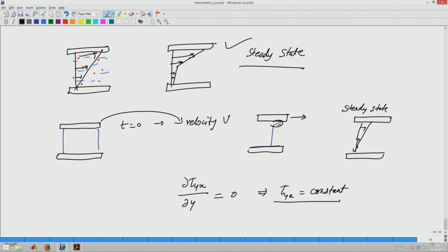There is a class of materials which show some density gradients, like what we saw in the case of particle gradients. Whenever such gradients are possible, it shows the shear banding phenomenon, because the material overall breaks into a low viscosity and a high viscosity regime, and therefore, into a high shear rate and a low shear rate regime.